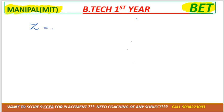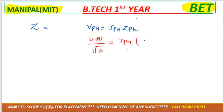Z is equal to how much? As you know the formula, VPH equals IPH multiplied by ZPH. So VPH is VL by root 3, so 400 divided by root 3. IPH we don't know, and ZPH also we don't know, right? Okay, so this is one of the equations, but they have given us the power.